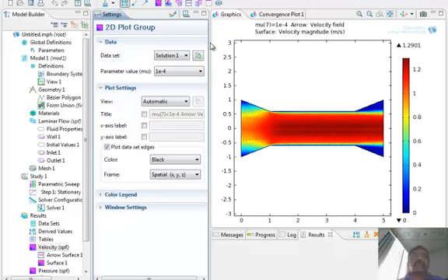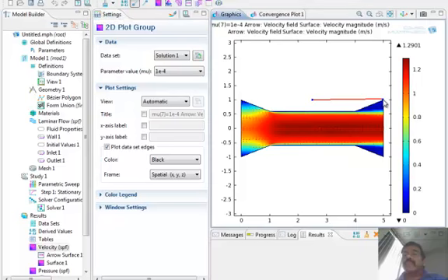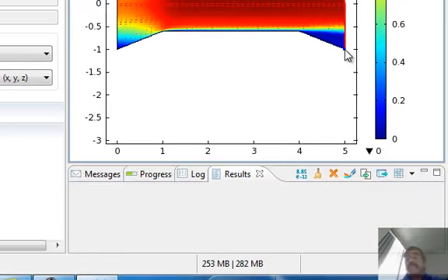The way to do that is select this, select the first point. Okay, so once you select that, it gives you a line. So you can leave that as the line and say, plot me the velocity variation along that line, for example. But I want to do this along the exit line. So I move the first point to there. And then I select the second point. And the second point is now the top in the middle. I want to put it down here. Okay. So I am drawing a line at the exit, and I want to plot the exit velocity to see what the exit velocity looks like.